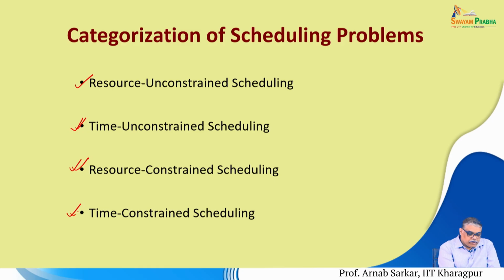Time constrained scheduling: you say that you cannot take more than a certain amount of time, and then your typical objective is to minimize the amount of resources that will be required to perform all the operations needed within the basic block with the least number of hardware resources.